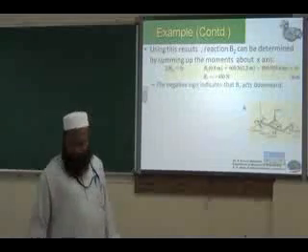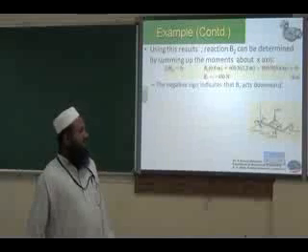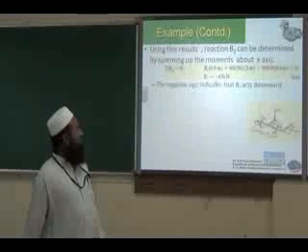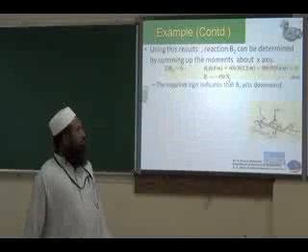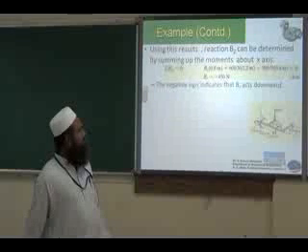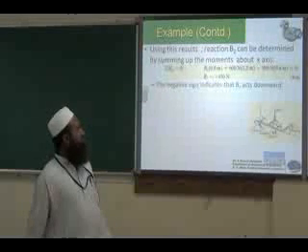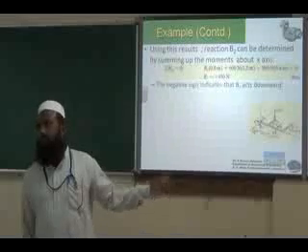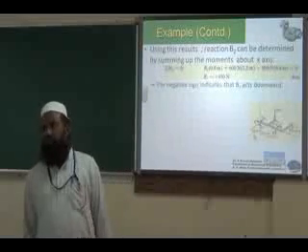Okay. So actually we have assumed Bz as acting upwards. Here we got a negative sign, minus 450 Newton by taking moment about x-axis. So if you take moment about x-axis, this Bz is minus 450 Newton. So we say that it is acting downwards. It is not acting upwards as we have assumed. Actually, it is acting downwards.